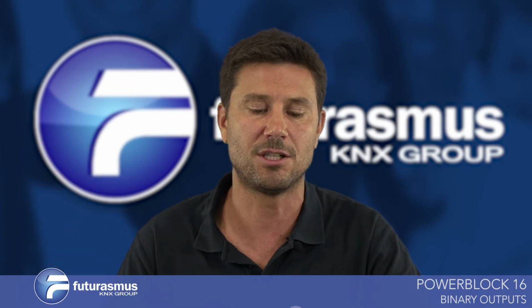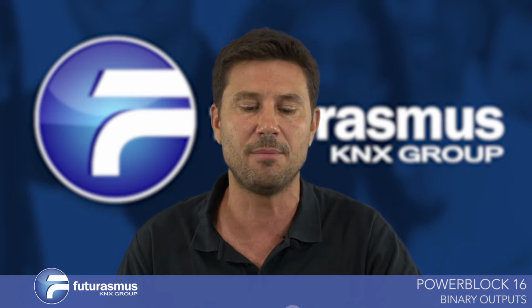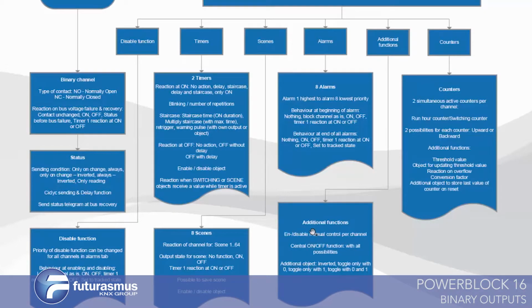You can also exclude a scene, which is also important. Some manufacturers don't have that possibility. And then most of the functions, almost all functions, have an enable-disable object, which is also very interesting because you can disable that, and you can also set the behavior of this enable-disable object for when the power goes down and the power goes up.